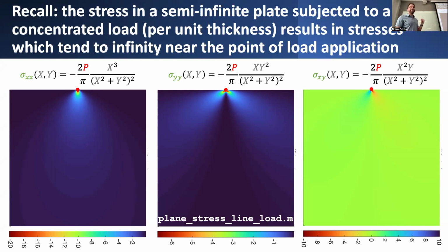So we can represent the solution in terms of polar coordinates, in terms of stress components reflecting that polar coordinate frame. So radial stresses and circumferential stresses, but that's a little bit awkward, especially if we really want to know things like, well, what's the stress distribution relative to our usual Cartesian coordinate frame? So you can take that solution and transform it into these Cartesian components simply by applying our usual stress transformation equations to go from one coordinate frame to another. And we get some distribution of stresses that look like this, expressed in terms of the usual sigma xx, sigma yy, and sigma xy components.